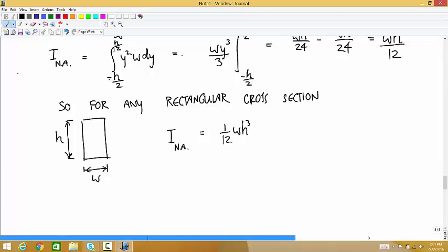And you can't drill on the C channels on truck frames. You can't drill on the top; you've got to drill only in the side when you attach things. All of those things, well, bending isn't the only thing they're trying to resist, but this resistance to bending is a big part of how any kind of structural element is designed.